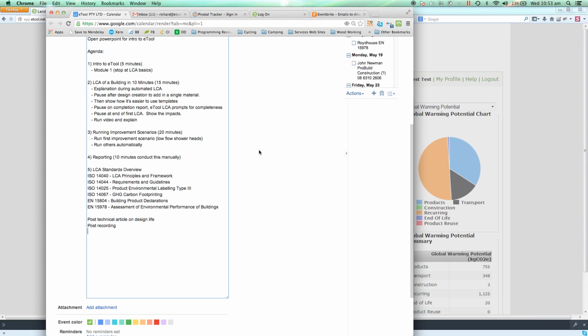I mean, if you're looking at utilising steel versus concrete in structure, and the cradle to gate stages are exactly the same, which would be probably quite unusual, but let's just assume you had two options for structural elements. One was steel, one was concrete, and the cradle to gate was exactly the same. You definitely run with the steel because you can feed that back into the economy, if it was just an environmental decision, whereas concrete becomes road base, it's effectively a waste material that gets downcycled at the end of the building life, whereas steel's actually got value at the end of the building life to go and be used in another, either get fully recycled at a steel plant or even get directly reused in some cases as well.